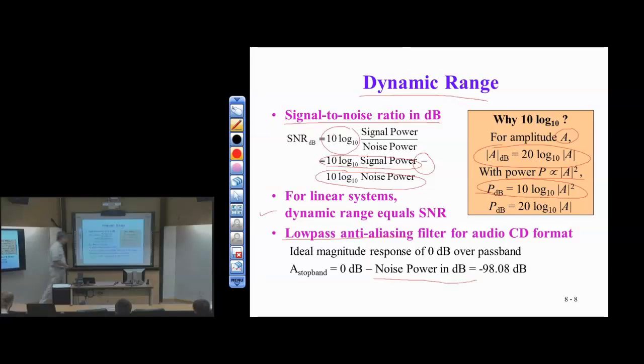Now for us, we know what that background noise is because after the low-pass filtering and sampling, we have quantization. So we know that at the output of the quantizer, the SNR here is already given. So here's the signal power, that's our full scale.